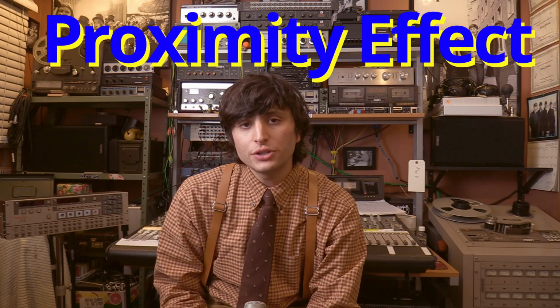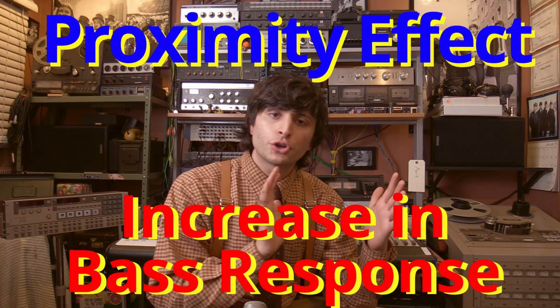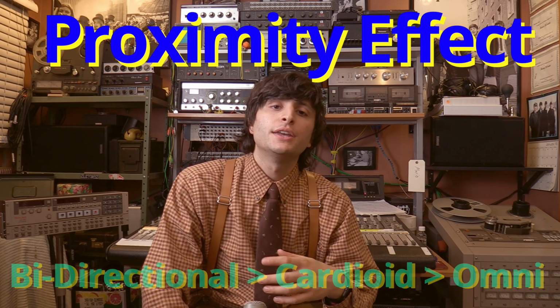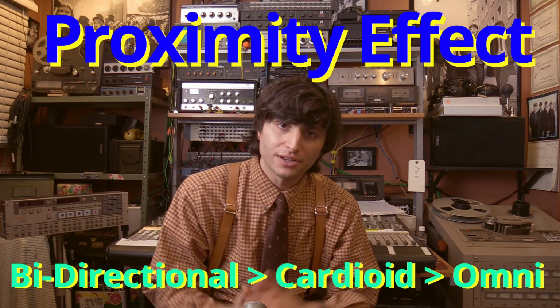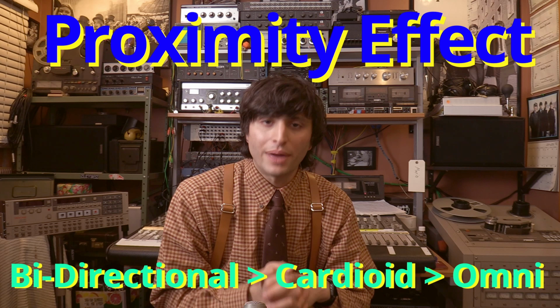The basics that you need to know, though, is the proximity effect is an increase in bass response as a microphone gets closer to its source. Here is a quick chart showing how the distance can affect the bass response of a microphone. This effect is going to be most pronounced in ribbon or bidirectional microphones. In cardioid microphones, you are going to hear it as well, but not to as much of a degree. And in omnidirectional microphones, you're not going to see this effect to any meaningful amount.